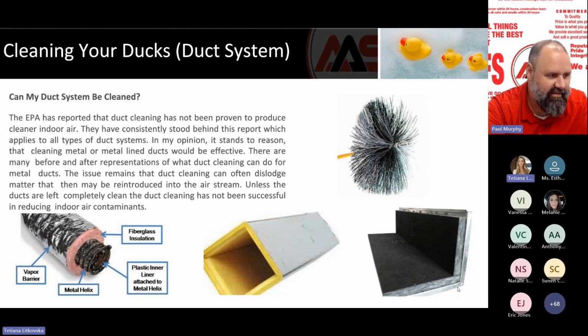So the flex ductwork, I don't recommend it because you can see that internal liner in the flex ductwork can become very brittle. It could break, and once you have a break in the liner, you're going to be leaking air out of that. And we don't want that to happen, especially if you have old flex. So I don't recommend cleaning flex ductwork at all, and I definitely don't recommend cleaning old flex ductwork. And if we're talking about houses, almost 100% of houses in South Florida are run with flex ductwork.